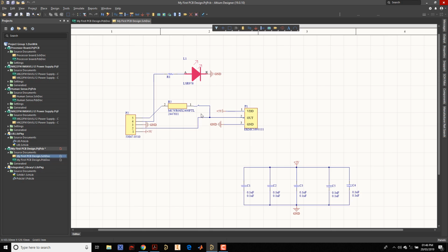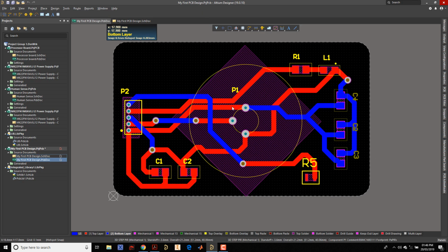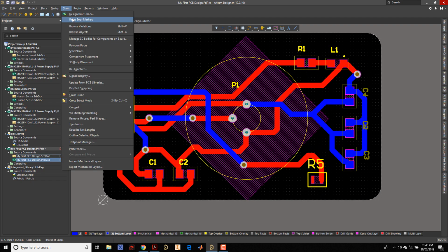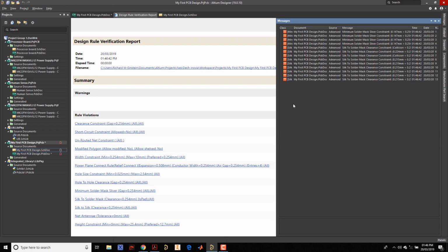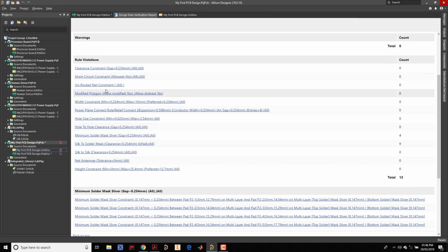The idea is, after you have done your schematics, exported it to the PCB, done the shape design, the part positioning and the routing, and done your DRC design rule check to make sure that everything is fine, you are not having any issues with unrouted nets. If the count is one or two, it means there's a problem and you need to fix it. If you click on it, it will show you where the problem is.